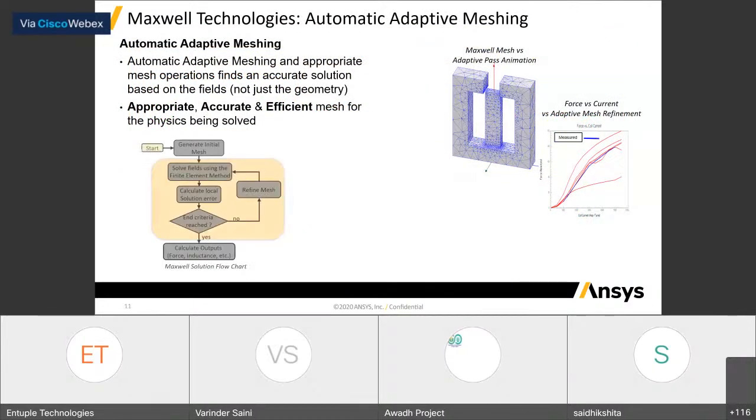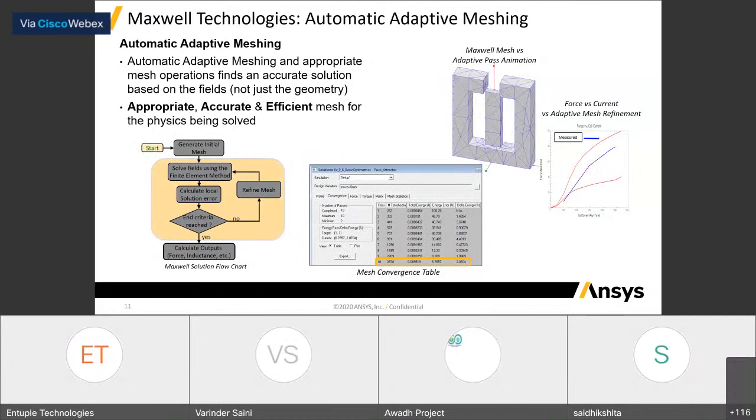So, the adaptive meshing that we were discussing. If you look at the GIF on the right side, you can see the meshing gets very distributed within the volume there. And you can see in the areas where the requirement is critical, more elements are put in. Okay, so this intelligent use of elements, or optimum use of elements, is what adaptive meshing gives you.